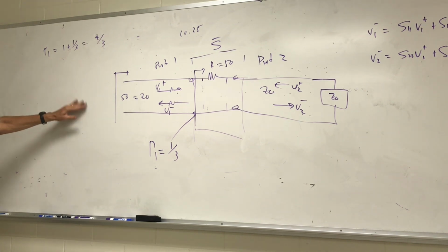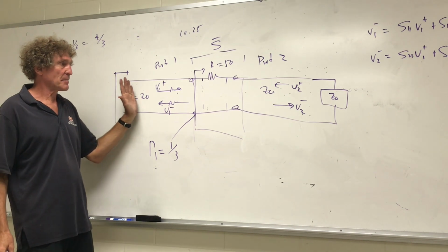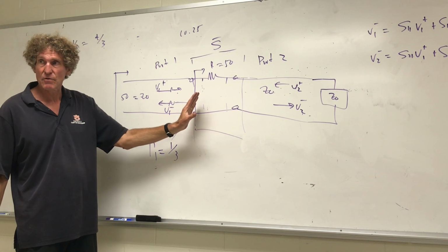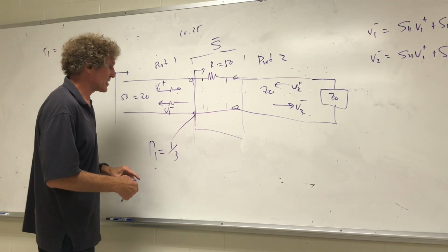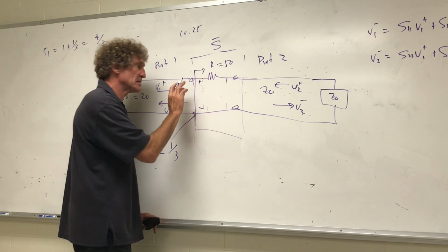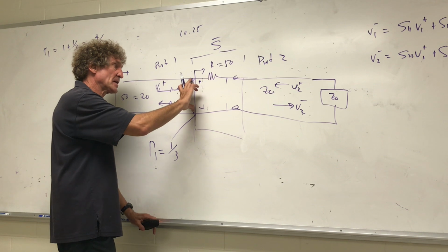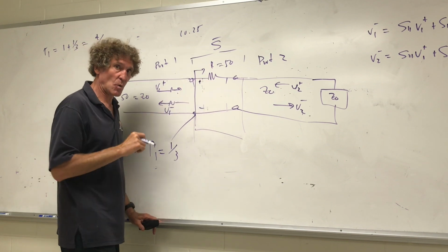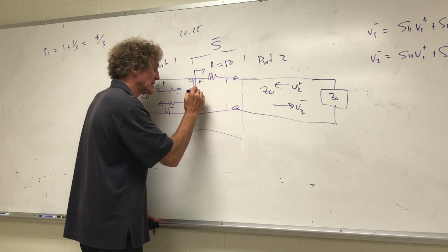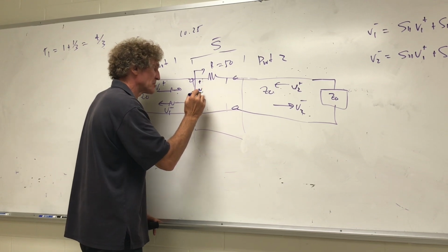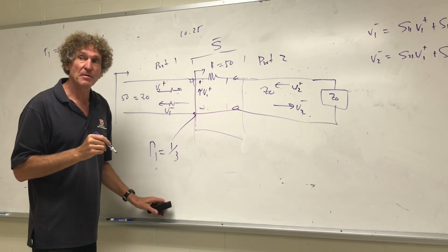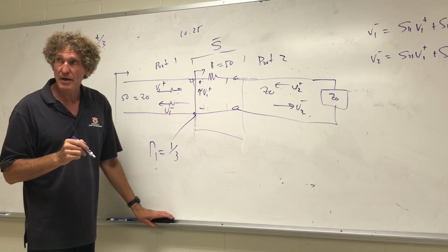Now watch this. So a signal comes in, V1 is coming in, some of it's reflected, some of it is transmitted. Please watch. How much is actually transmitted? Well, the transmission coefficient says that the transmitted signal just beyond where that transmission line is attached to those wires will require that the signal transmitted right here be tau, the transmission coefficient, times V1 plus. Do y'all see that? This is very important. Are you good with that?